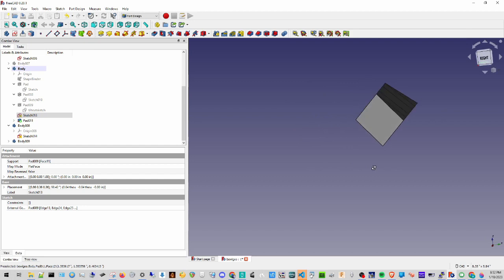If we move around to the back of the stave, we have another trapezoid shape on the back. And again, some of the lines we've been looking at: this line here, that's in yellow, that's our inner L, the L of the first square we looked at. The second square, that's this line running across the top here. And then the third, outer square is this edge along here. That was the third L that we figured out. There's also a bottom side, which is another trapezoid, and we see through inspection, and it makes sense when you think about it, that the miter angle on all the trapezoids is the same.